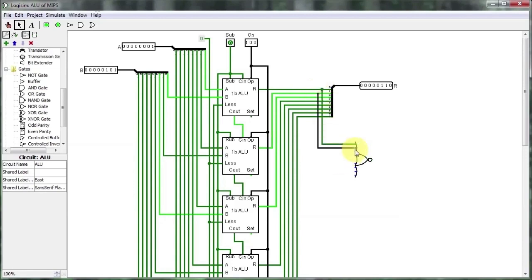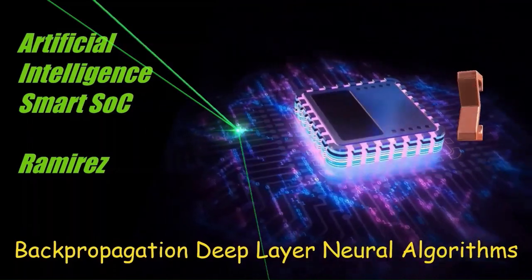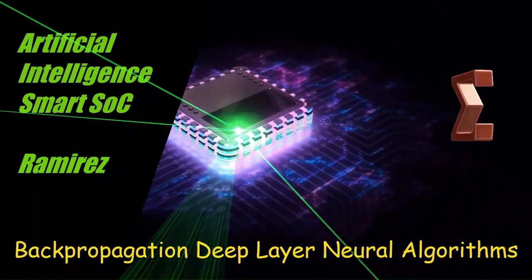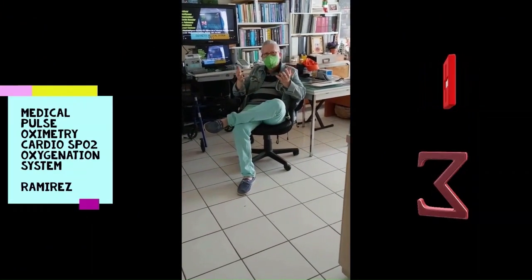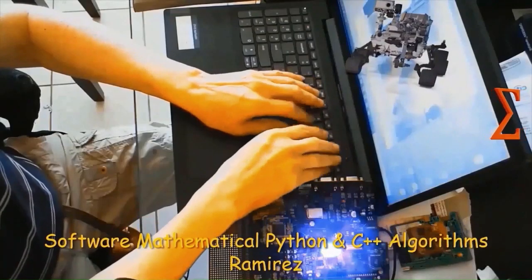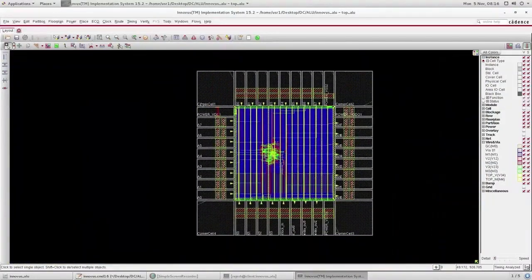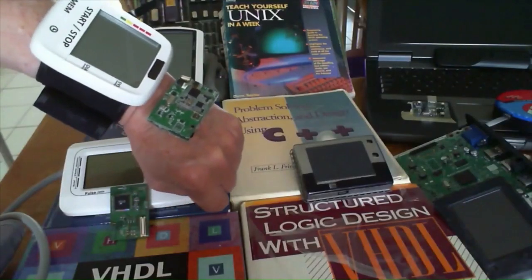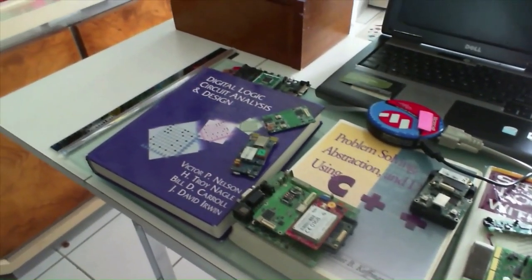The routing program receives guidance from the clock optimization program for nets in clock and other timing critical trees in the form of floor plan routes. The routing program breaks each of these multi-pin nets into a group of point-to-point subnets. Each of these subnets is then routed to match the delay selected by the clock optimization program as closely as possible to achieve the desired electrical and noise characteristics.